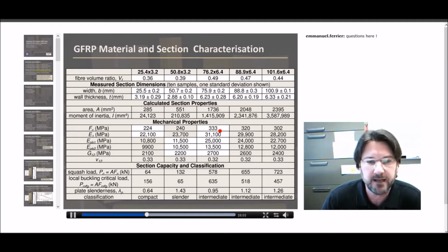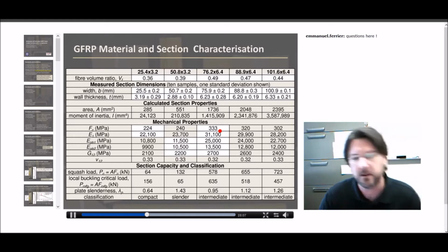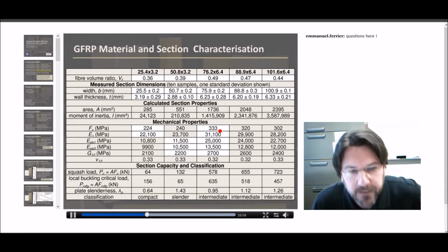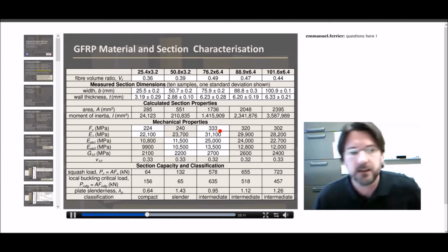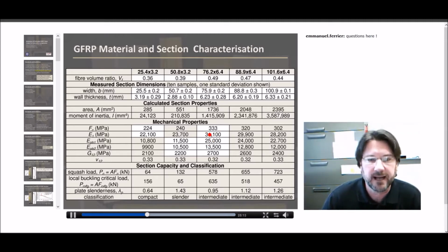The remaining data was calculated based on laminate theory, actually on the Eurocomp equations, and calibrated to the experimentally determined values. From these, we can calculate both the squash loads of the individual sections and the critical buckling loads based on the plates making up these sections.